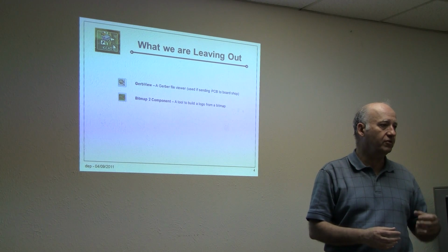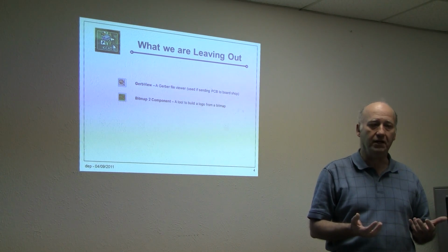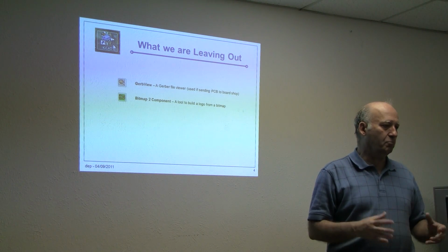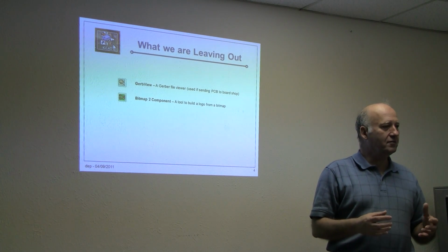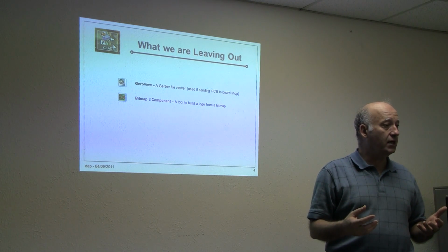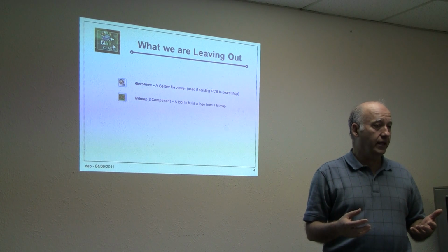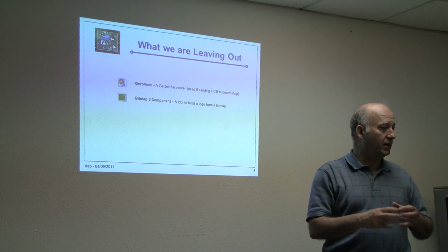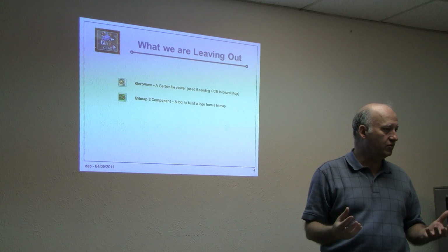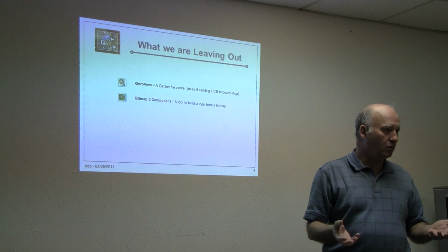So for example, let's say the standard resistor you don't like. I know Richard likes big pads. So you can modify or create a footprint that has big pads but has the spacing and the symbol that you want to use.